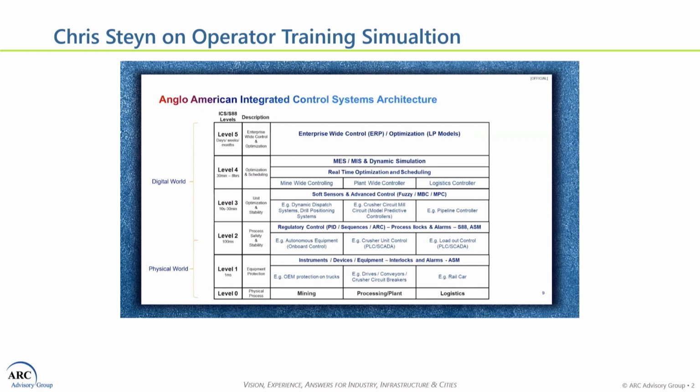Level 2, part of level 2 is the actual PLCs, and the other part is the software, which comprises the sequences, the PID, the control, the base layer control algorithm. Level 3, which is typically at an execution of between 10 seconds to 30 minutes, is your advanced control. We standardized on the Honeywell Forge software. We still call it Profit. I believe it's moved on to Honeywell Forge.